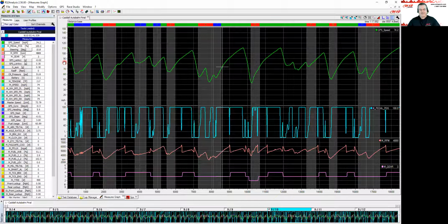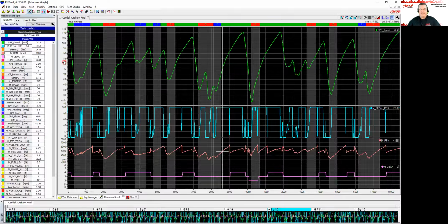When you double left click on any channel, it does a best fit for any channel that you're using. Okay, that is a huge time saver, and as we teach people, and certainly as I do data analysis all the time, that is a function that I use all the time, and it's very, very helpful and really does speed up your ability to do data in a hurry. So keep that one in mind. Double clicking on the scale bar is a powerful tool.